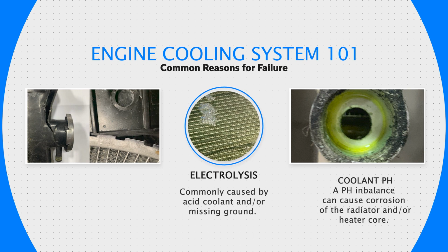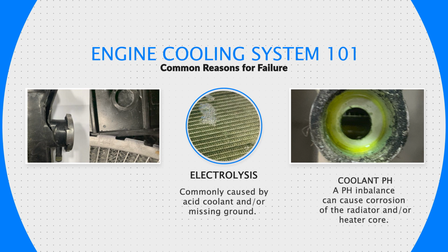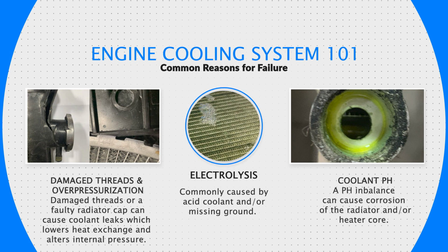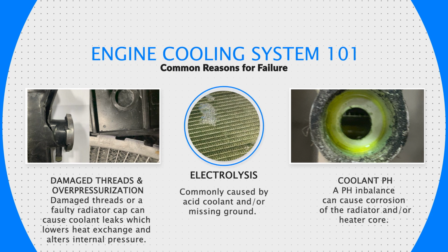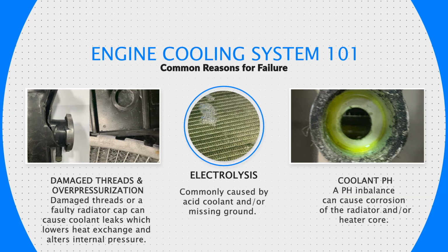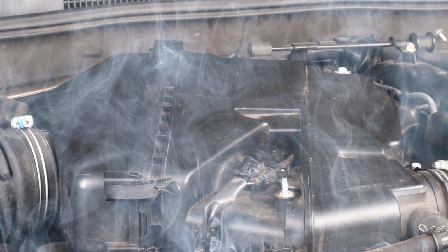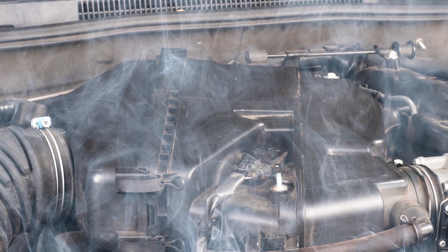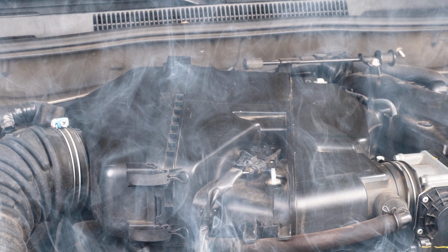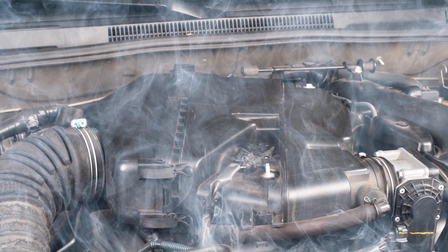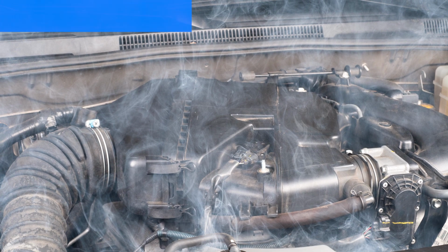Damage to threads weakens the fitting connections, causing leaks. Extreme pressure in the radiator can be caused by a faulty radiator cap, lack of coolant, or faulty components that reduce heat transfer. If the radiator is unable to transfer heat, the engine is susceptible to irreversible damage if it overheats. These components have plastic parts that can melt and break, hence contaminating and blocking coolant flow. If one of these components fails, the radiator and interlinked components will likely fail as well.